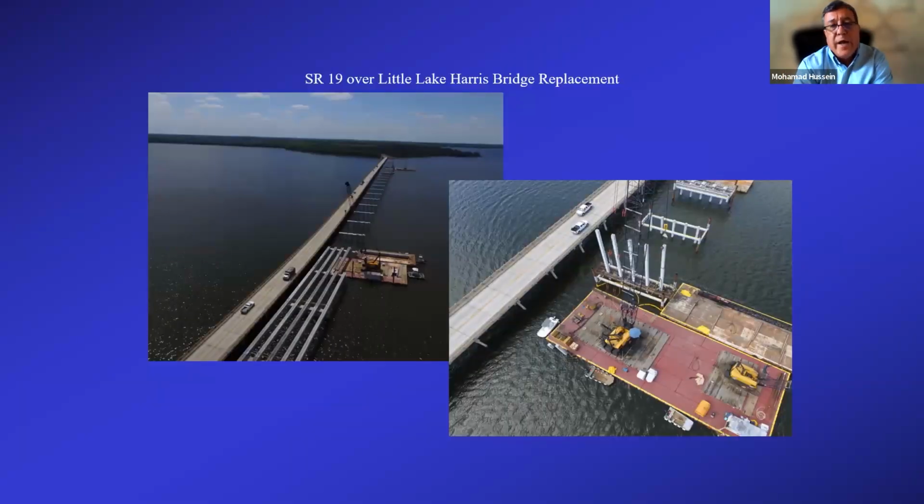So this is a project, actually a design build project, where the contractor and the engineer team decided to utilize both. They utilized the probe, they call probe piles, or let's say test piles, along the alignment of this bridge project, and then utilized 100% testing. And the contractor said in this case that it's the best pile driving job he's ever done because he has the benefits of both the test pile program information and the 100% testing that helped in the scheduling and in the cost of it.